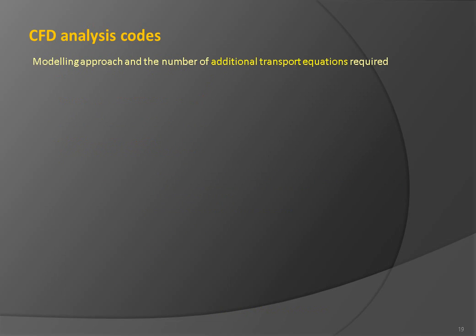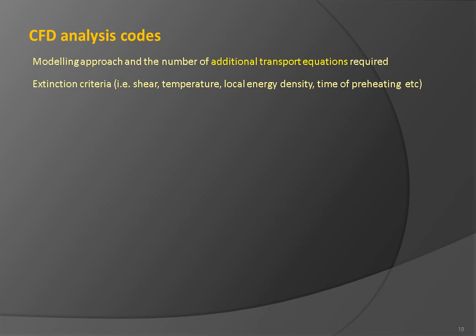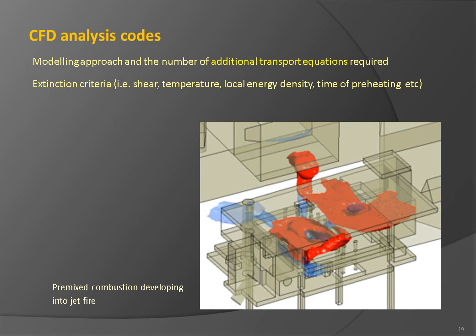First area of differentiation that we will look at is geometry resolution. A practitioner needs to understand which geometrical features to resolve and which to represent through subgrid models, and which to completely exclude. The top left figure shows a case where the numerical model fully resolved the geometry.